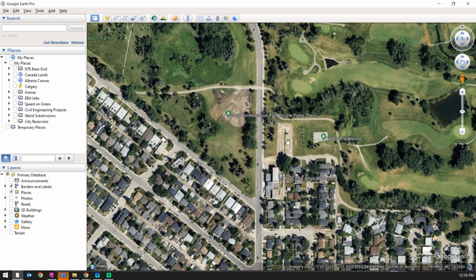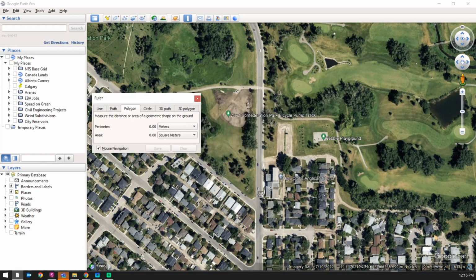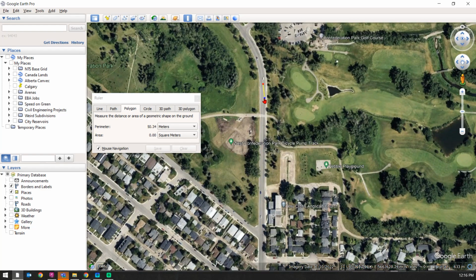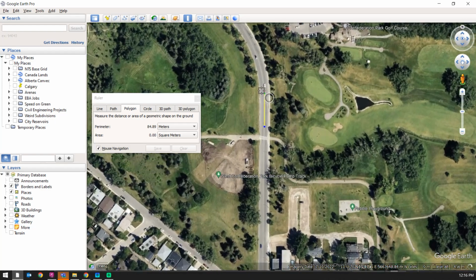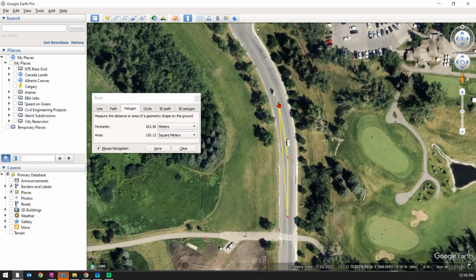So if I have a sanitary line that is going north, right in here we have a tangent section that is way over 185. So let's shorten that. So we have a straight section here, tangent is 84 meters. If your pipe continues around the corner, okay, clear that. So if we continue around the corner, your pipe will start to appear curved. In Civil 3D, we'll draw it as one long curved pipe.